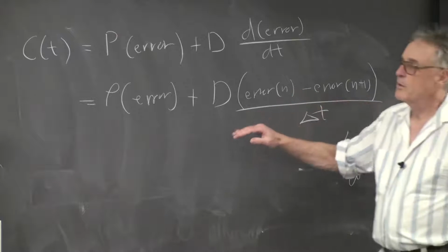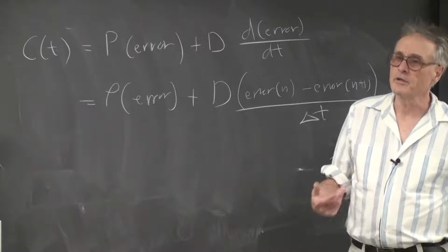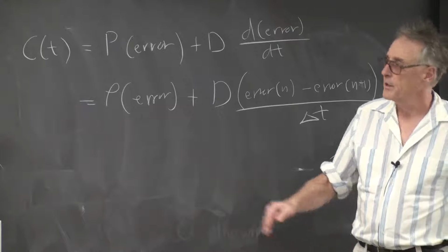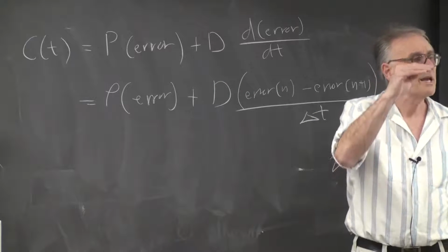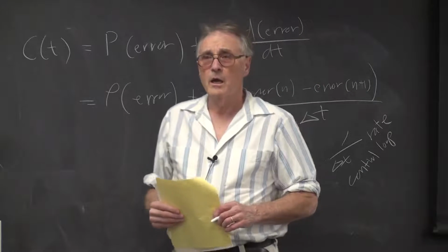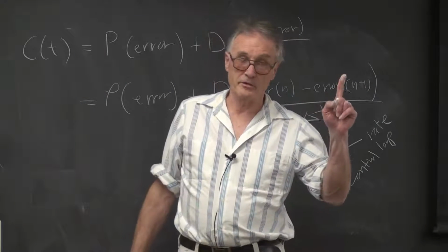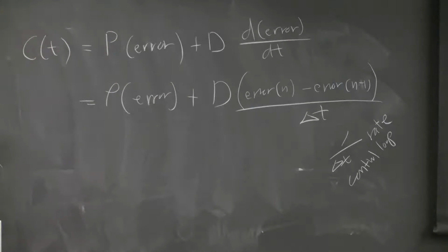And the derivative term should help with high frequency stability. Adding a little bit of differential term in, making a small d constant, will help stabilize the system at high frequency. High frequencies are near an edge. Whenever you have an edge, whenever you have a step, you have high frequency input, right?